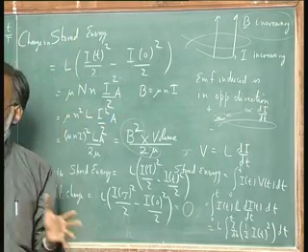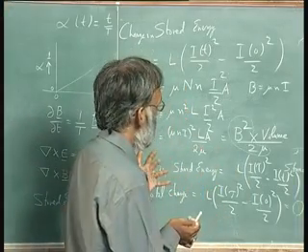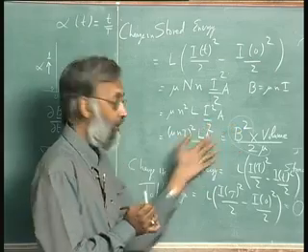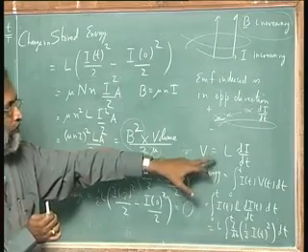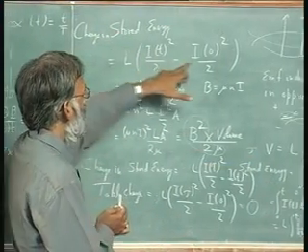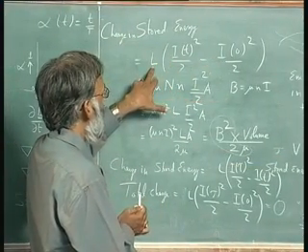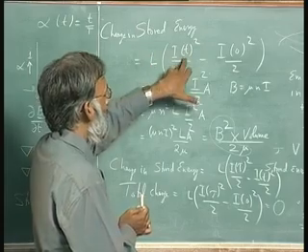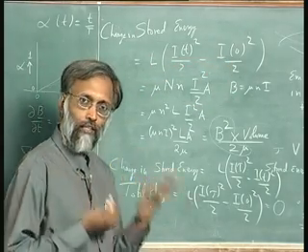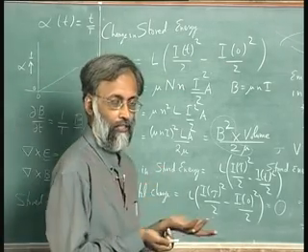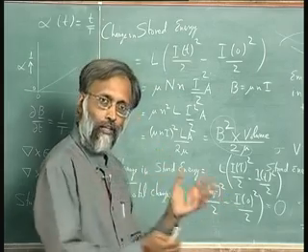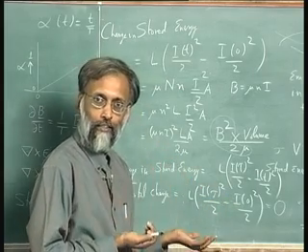It is that we have a known device where we have known magnetic field. In order to increase the magnetic field, we found we had to do work. The total work we had to do to bring a current up from I of 0 to I of t was 1/2 L times I of t squared minus I of 0 squared. We know that this is a conservative kind of change in energy, because if I bring the current back down to 0, I get all the energy back. It is not a resistor in any way.